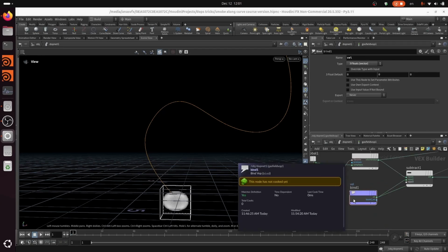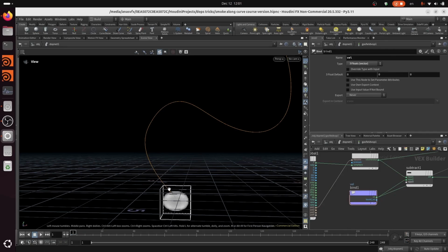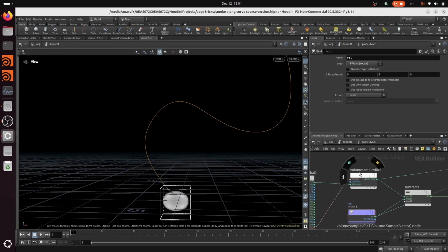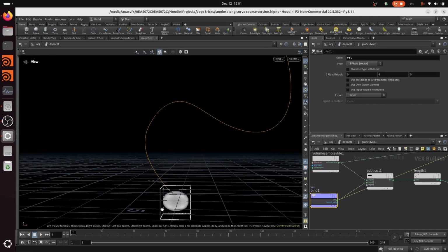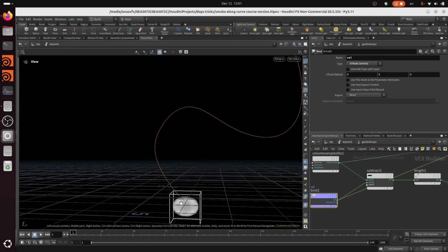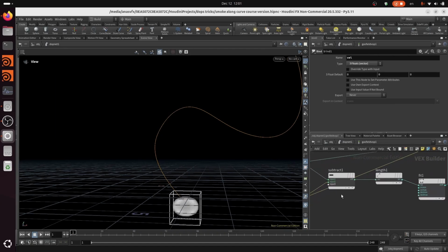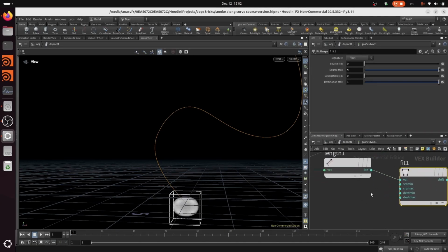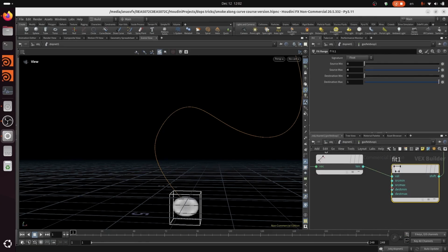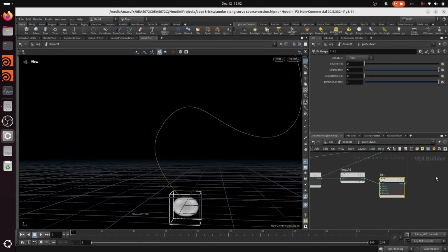Okay, and if the smoke adheres too much to our volume sample from the soft guide, then the velocity field from the simulation is going to be dominant, because this will make our smoke float more naturally by the temperature and the buoyancy. And this is going to be a balance here, and surely you can promote this source max parameter, so this can be controlled by the user.